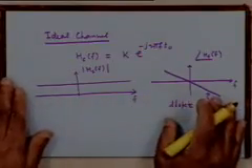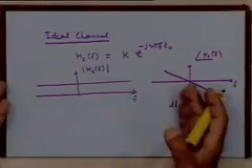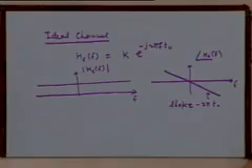Of course, this kind of ideal channel is too much to expect to be available in practice, right? It's not even required if you really look upon it, because in real terms you will be transmitting a signal of some finite bandwidth, not of infinite bandwidth, right? So in that case our concept of an ideal channel can be made less stringent. As long as these characteristics hold within the bandwidth of the signal, we should be quite happy, because what happens outside is of academic interest only, because the signal does not have any frequency components beyond some value, right?